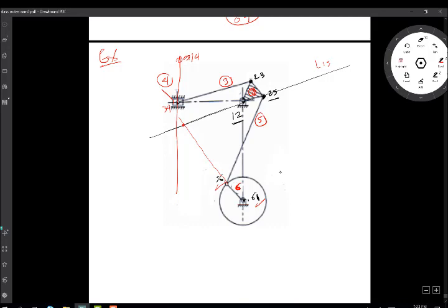0.34. This here is 0.15. That's another locus for 1,5. That's 1,5. So you know 5 actually rotates instantaneously at this point in time, not always about this point. This is the pole for 5. And you can tell that link number 5 does general motion. This link does general motion because both ends move.